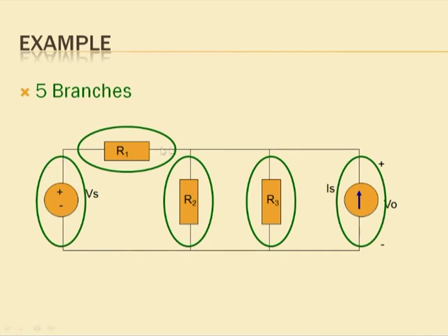So here you can say that these 5 elements are given in the circuit, and that's why the number of branches are 5. Again remember that the line which is drawn to link or to connect the 2 elements of the circuit will not be considered as the branch. So the total number of branches will be counted like this. So in this circuit we are having the total number of 5 branches.